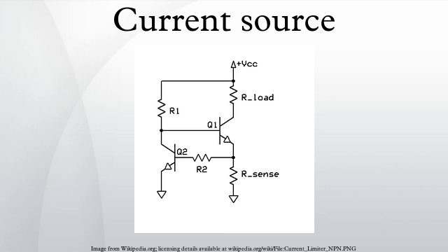The INIC acts as a second current source passing helping current IR through the load. As a result, the total current flowing through the load is constant and the circuit impedance seen by the input source is increased. However, the Howland current source isn't widely used because it requires the four resistors to be perfectly matched, and its impedance drops at high frequencies. The grounded load is an advantage of this circuit solution.